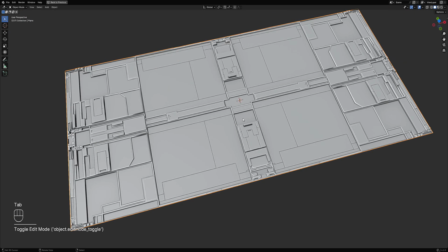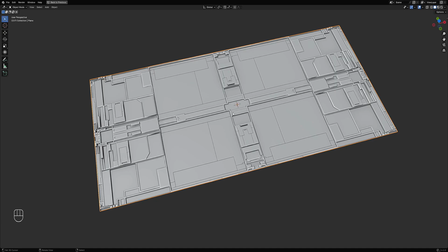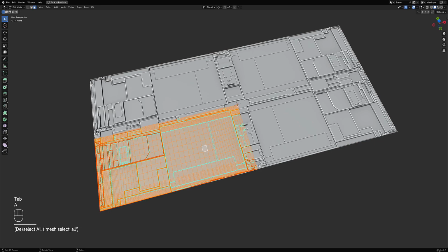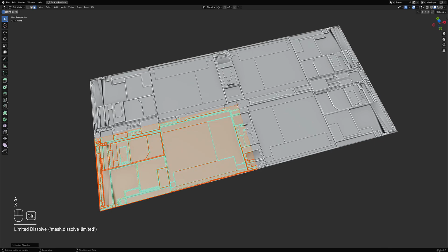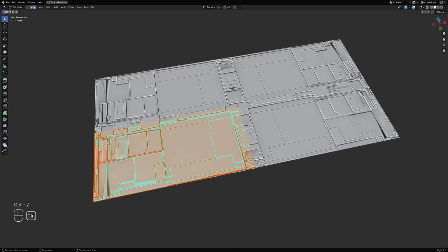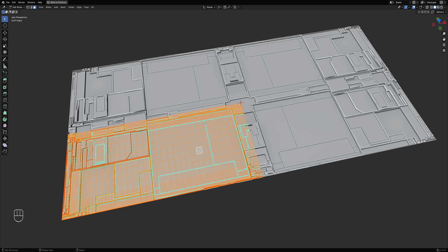And for hard surface, that's going to be just background assets like door opening, closing, or crates or sci-fi panels just being static. It's not really important for them to be quads. You can just turn them into n-gons and triangulate, and then they're going to be okay. They're not going to smile, walk, bend, or twerk. So it's okay for them to be n-gons because they're not going to be animated.